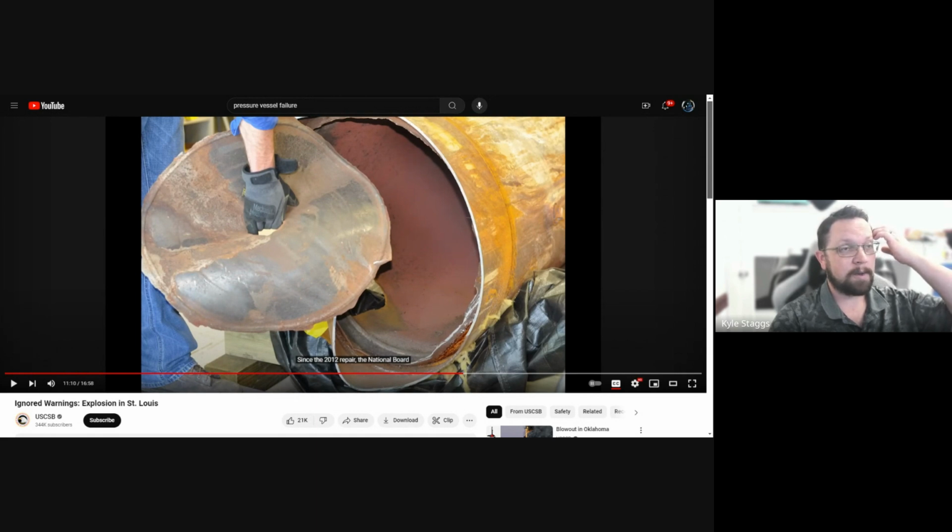The professional welders that I know would absolutely throw a fit and say, no, you have to completely replace the entire base of this, and it's going to be much more expensive because we have to remake all of that curvature. So instead of being lazy and cutting corners, all of the welders I know would have taken issue with that, but it thinned to such a high degree that it looks like here the repair piece is 1/4 inch thick and the piece that they welded it to is less than 1/8 of an inch thick because of that corrosion. That's really bad. That's really bad.